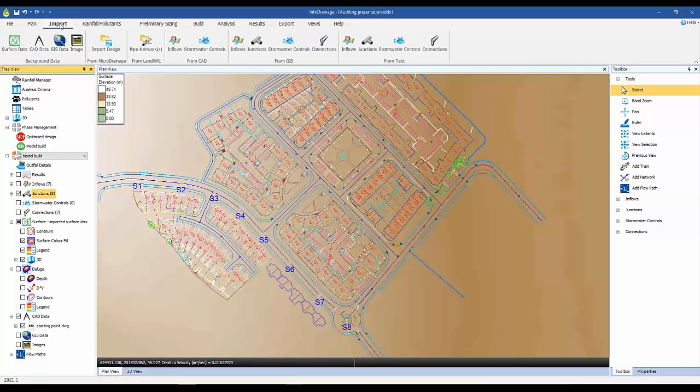I will also mention at this point that it is possible to import a microdrainage study. So you might have a microdrainage study that you then want to audit within InfoDrainage. That's fine. You will get slightly different answers. They should be similar because the two methods of calculation are certainly similar, but there will be some differences, as I say, because we've made the calculations more flexible. There's more possibilities for things that you might want to include, and I'll mention that as we go through.